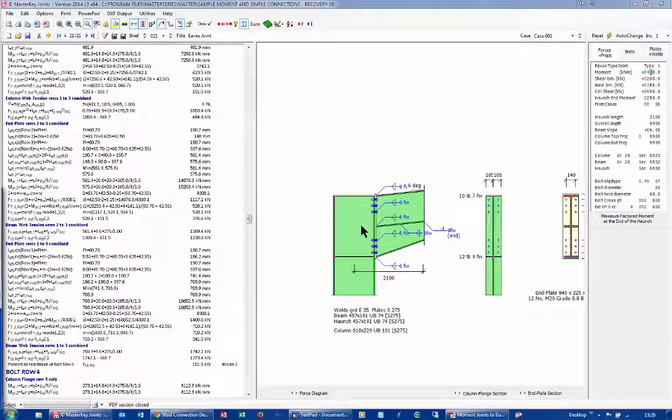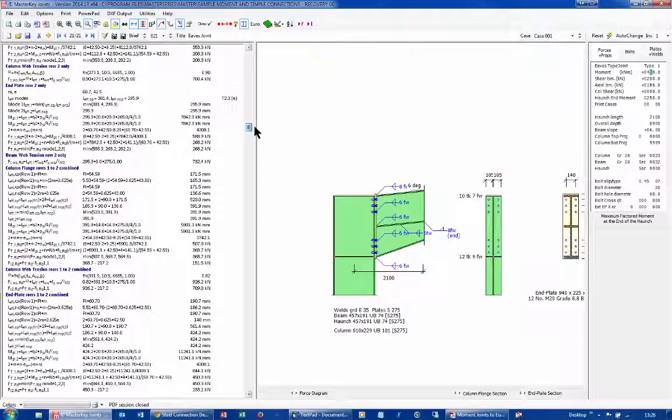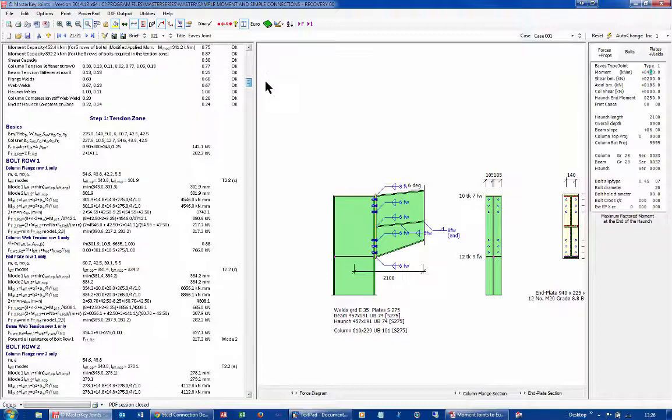In the column and beam webs, we have this beta value. So if we look back up to our calcs at row 1, easiest, let's not look at too many calcs at first. We have in the column web tension, we have an omega value and a beta value. And the omega value can frequently be less than 1. 0.7 is actually a typical value. In this case, it's 0.88. And this reduces the capacity of the web. And the omega is, I think, really based on the difference between the moments on either sides of connections. So on double-sided connections, it has an effect.